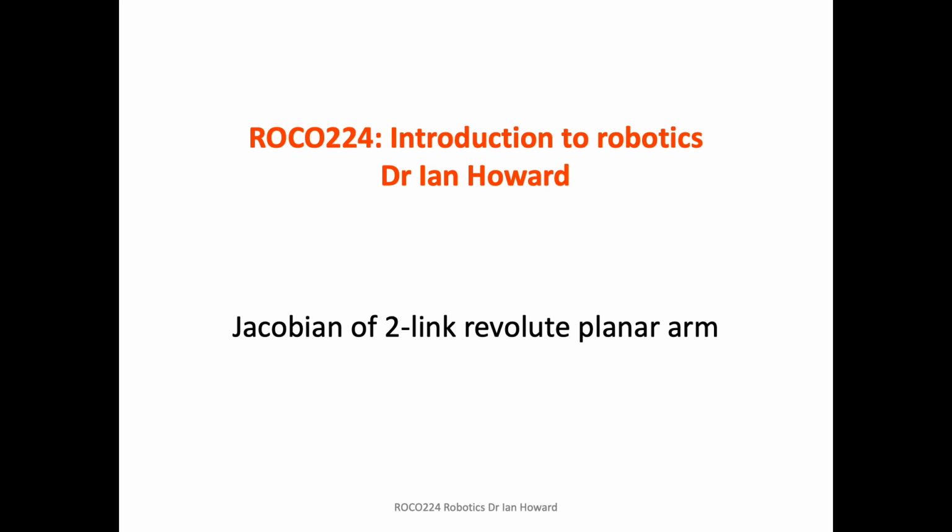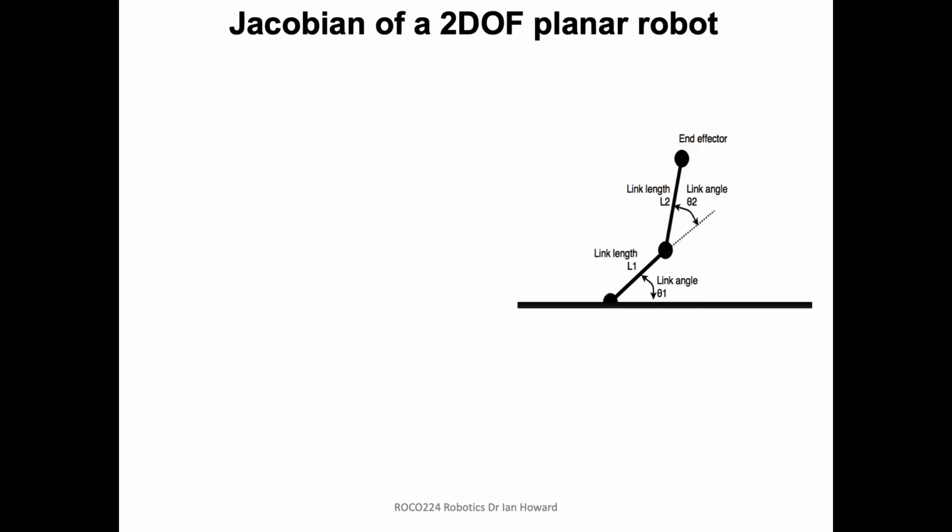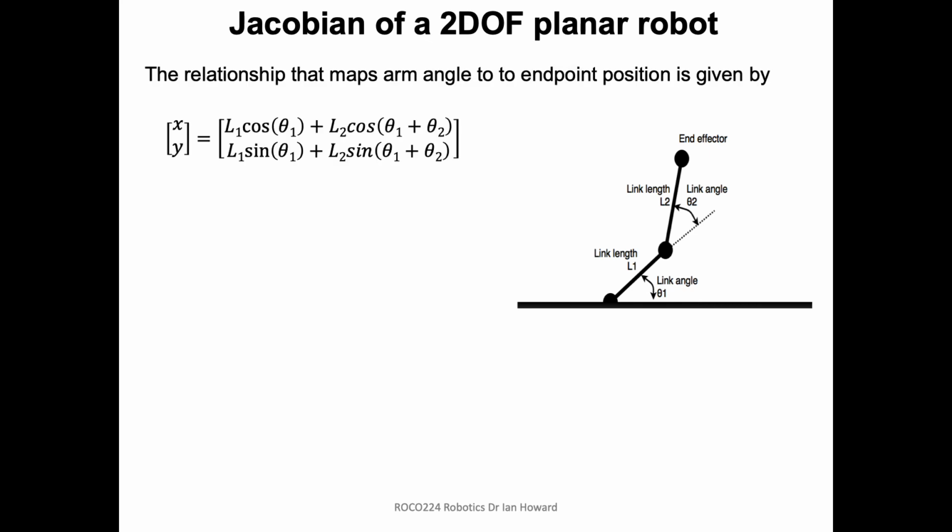Now let's do a two-linked revolute planar arm and do the Jacobian of that. So it's a little bit more sophisticated. In this case, again, we're just going to write down the expression for x and y. Obviously, we've spent the last so many lectures going through Denavit-Hartenberg and doing these things from first principles. So if it was a more complicated system, what you'd first do is work out the endpoint of the system. We'll do the forward kinematics, and look at the position part to get the relationship I need for this particular analysis, which is the x and the y in terms of the control parameters.